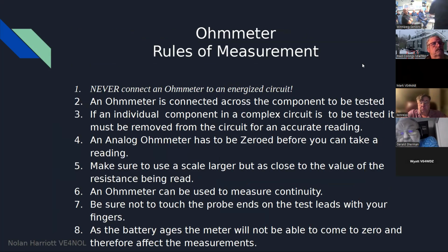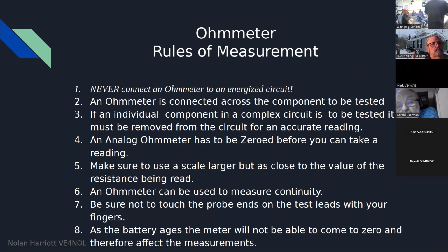Ohm meters. Rules of measurement: never connect an ohm meter to an energized circuit. Fluke meters are a little bit more forgiving. They'll scream and beep and flash lights at you. But a lot of the less expensive meters, if you have it set to ohms and you put it into a live circuit, you're probably going to let the smoke out of it.